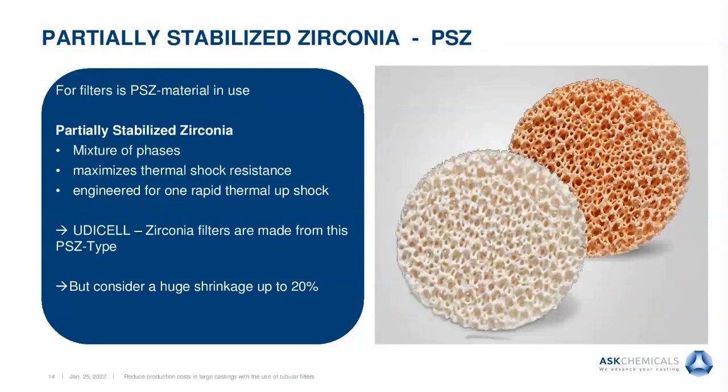It is capable of withstanding thermal shock from room temperature to 1700 degrees centigrade without creeping or melting. It is chemically inert and therefore able to withstand the corrosive effects of the alloys and the slags with which they come in contact.